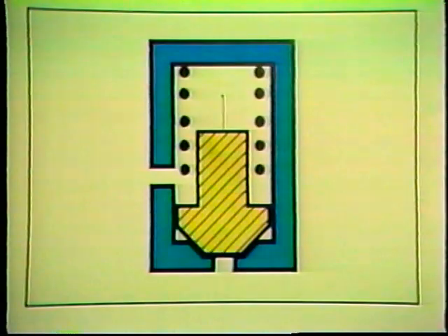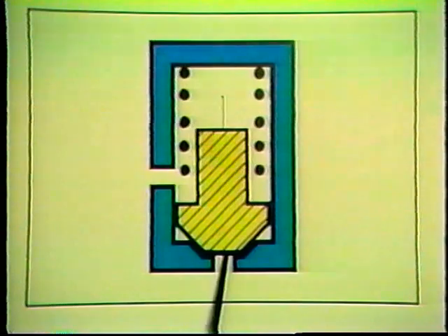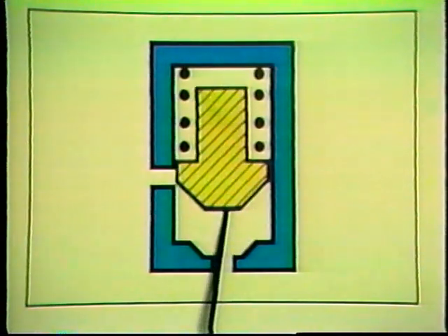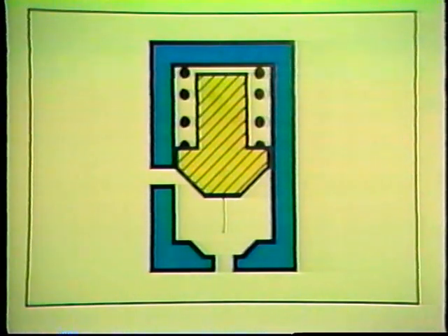Suppose that we have a pressure switch controlling a compressor and the pressure switch fails with the compressor running. What would happen? Well, if the compressor continues to run, the system or tank pressure will build up. When the pressure of the air against the poppet is greater than the spring force, the spring will be compressed and the poppet will move off its seat as you see here.